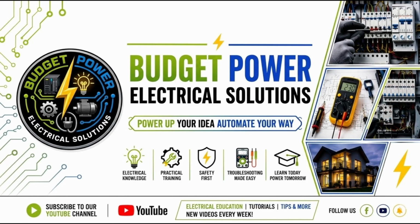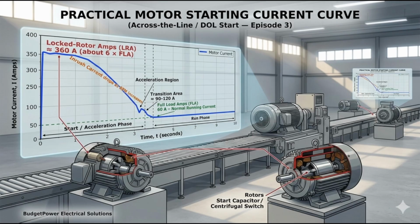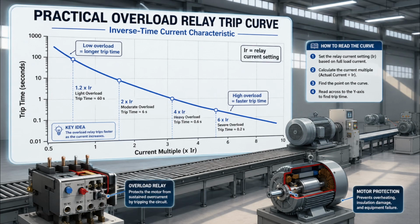In this episode, we're going to understand the current time trip curve of a thermal overload relay. An overload relay does not trip based only on current. It also depends on how long that current continues. During motor starting, current can be very high for a short time, but the relay must allow the motor to accelerate without unnecessary tripping. So the key question is, how much current, for how long? Let's look at the trip curve and understand what it really tells us.